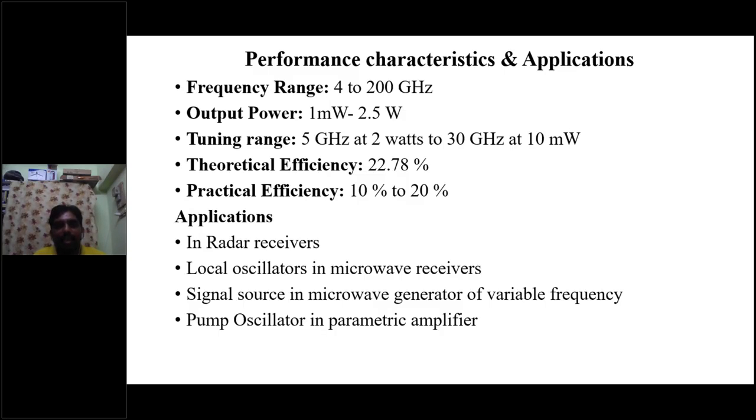But otherwise they can ask to explain the mathematical analysis of the two-cavity klystron amplifier. Your mathematical analysis means you draw a graph separately, one side input cavity and the other side output cavity, and using the mathematical expressions at different times, we can find out AC power and DC power, the ratio of those two. We find the efficiency for the two-cavity klystron